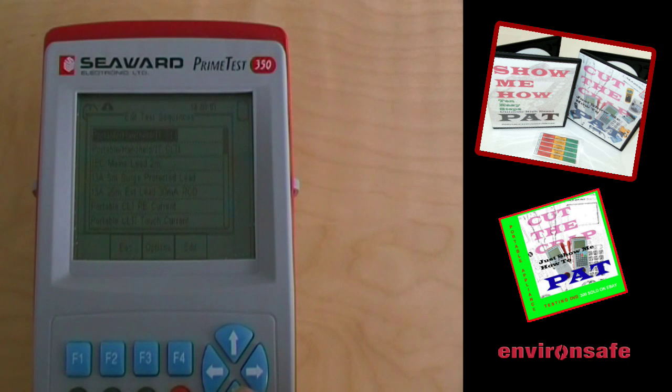And let's say we want to edit portable handheld IT class 1. We want to use the sequences in that, but we want to have some additional ones. Now I would suggest that you leave that one completely alone. Go into options though for this one, and we'll copy the sequence. F4 will OK that, and that actually copies the sequence and puts it at the bottom of your menu, but at this stage it still has the same name as the original sequence.